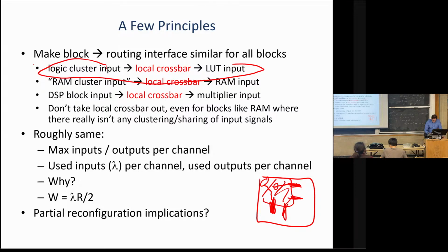What we'll do is, for signals that are coming in, we'll always insert a LUT. Okay, so it does start at the output of a block, and for signals going out, we'll insert a LUT as well. So it ends on the input of a LUT. So it's going to look the same difficulty as everything else. If you look at the design, you go, why do I have these LUTs that just copy their input to output? From a logical perspective, it doesn't make any sense. You just added a little bit of extra circuitry. But from a reliability perspective, it's much nicer for the CAD tools. So anyways, we came up with this.